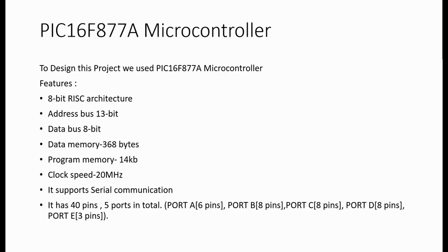Now coming to the project. To design this project, we used the PIC16F877A microcontroller. Why only PIC16F877A? Because with MPLAB, it has timers and interrupts suitable for real-time control. It has a built-in ADC and sufficient input/output pins for controlling multiple devices. Features of